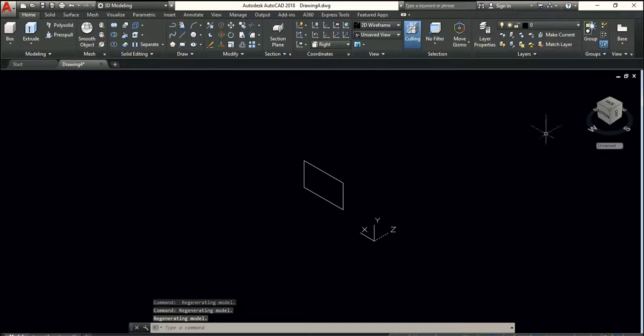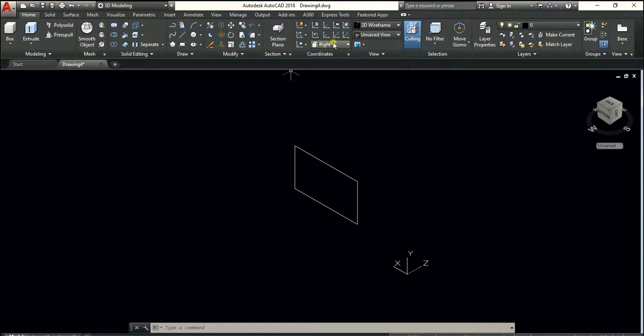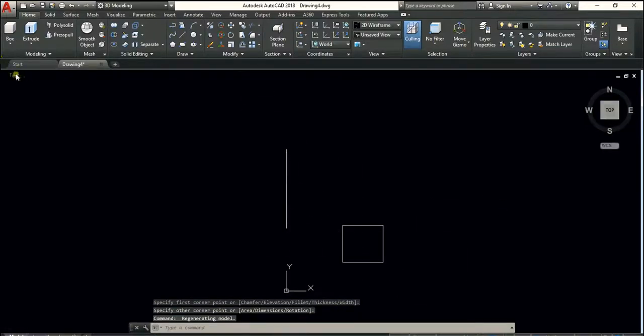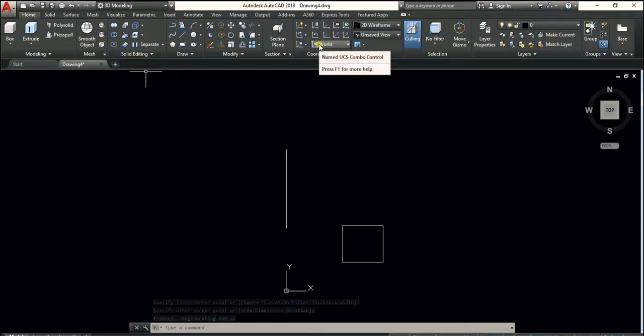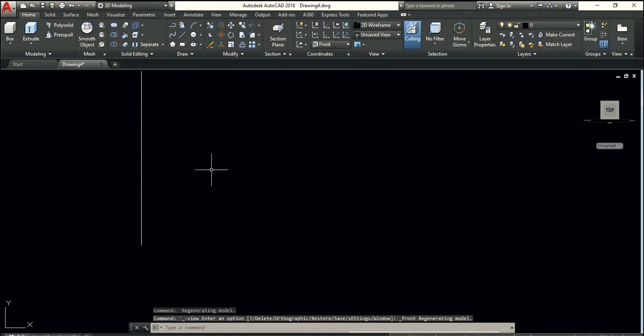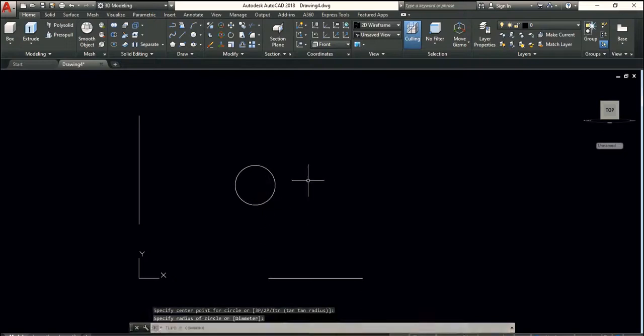You'll get to understand what this does. It just constrains your drawing to a particular plane to draw. Because by default in your home, if you try to create anything using the home view, it's going to constrain it to the normal home, which is the XY, which is the top view normally. So this changes your coordinates control. If you come here and change this to your front, it changes to front, and that means you can create anything in the front control.